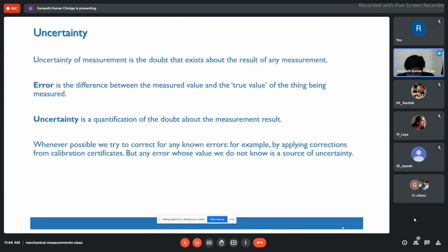So now we will move on to uncertainty analysis, which is one of the most important things that we have to conduct. As a PG student or an experimentalist, you have to always tell what your measurement is, what the uncertainty in the measurement is, and what the range of the error is that you are going to get out of the instrument. What we have found out so far is how to estimate the deviation or error, each individual uncertainty of a particular instrument. For a pressure measurement, how much is the error? For a thermocouple, what is the error?